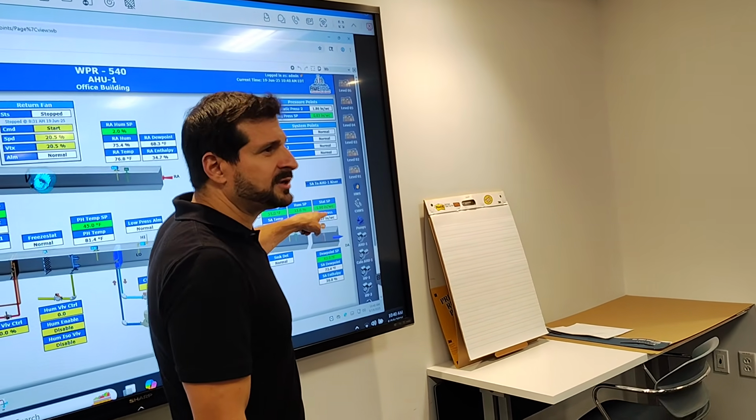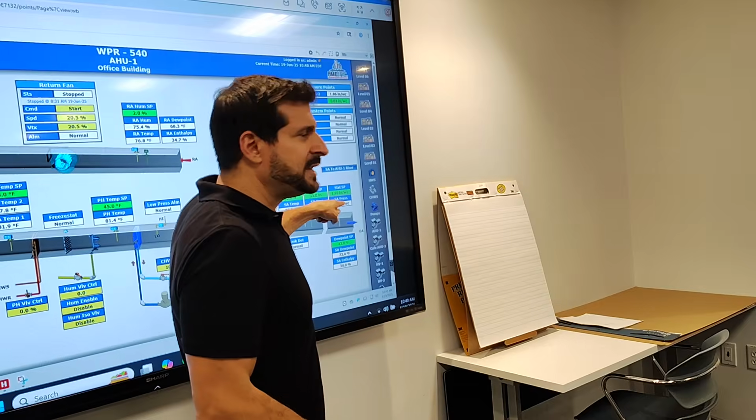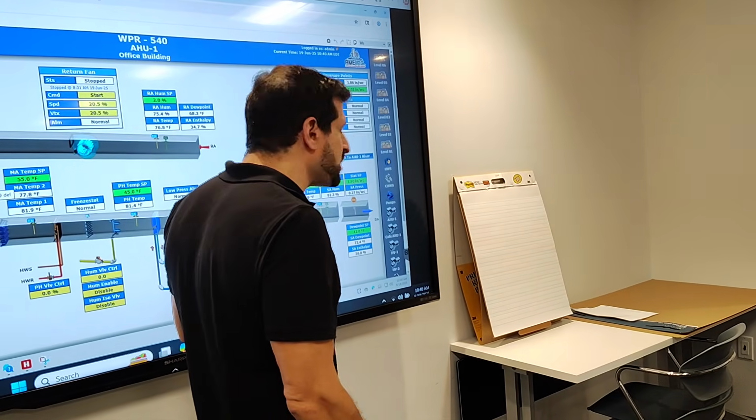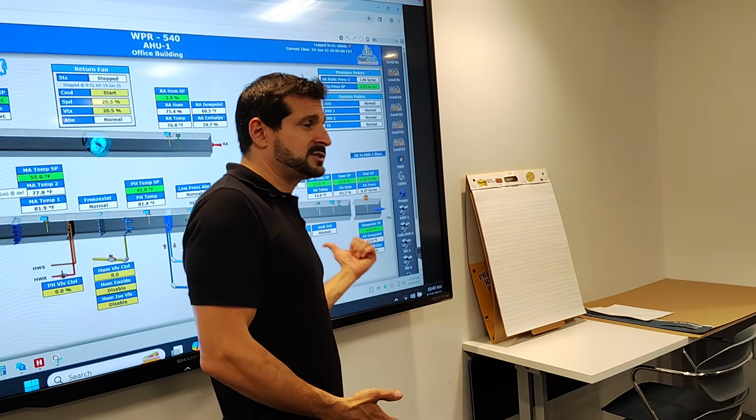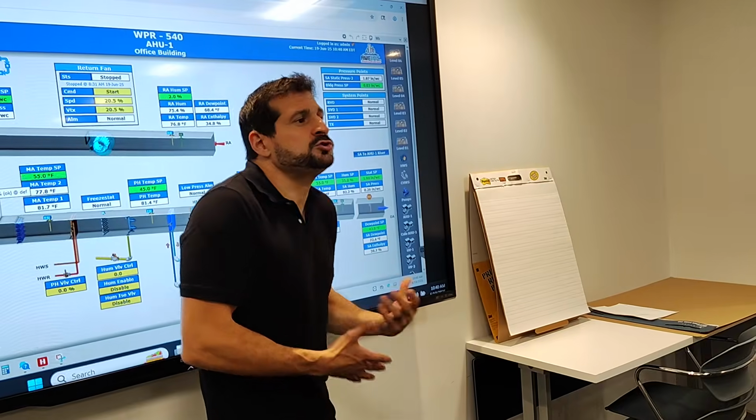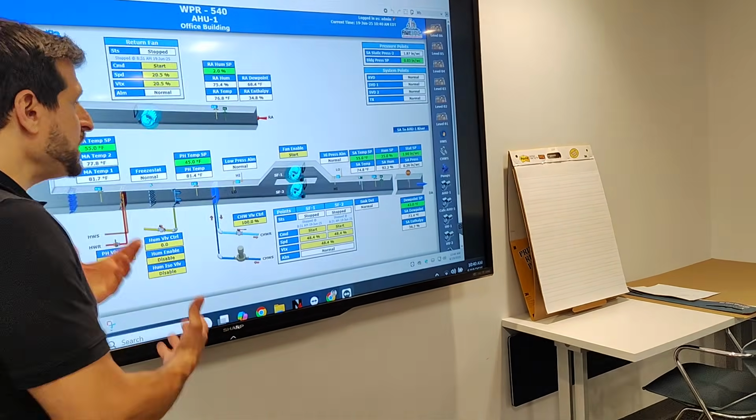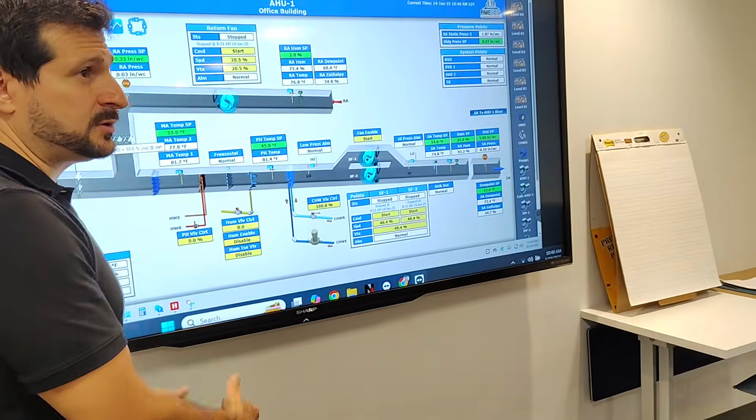What happens if something closes and it goes to 2.3? Is it going to take 30 minutes to get that? You might blow up ductwork with this kind of a control loop. There's no response here. Right? So this is clearly untuned. Why would you blow up the ductwork?